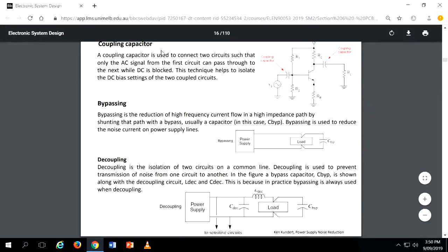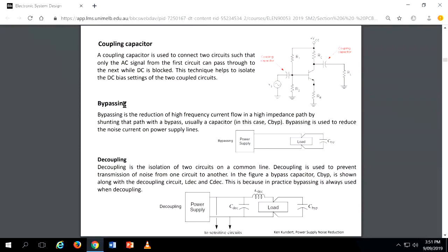When somebody is talking, you have to make sure, because they may use decoupling as bypass. So you have to ask them where they are connecting, and then you can make up your mind. Coupling usually means coupling capacitors in the amplifier for isolating DC. Bypass means that you are connecting near the IC. Around the IC people connect bypass capacitors.